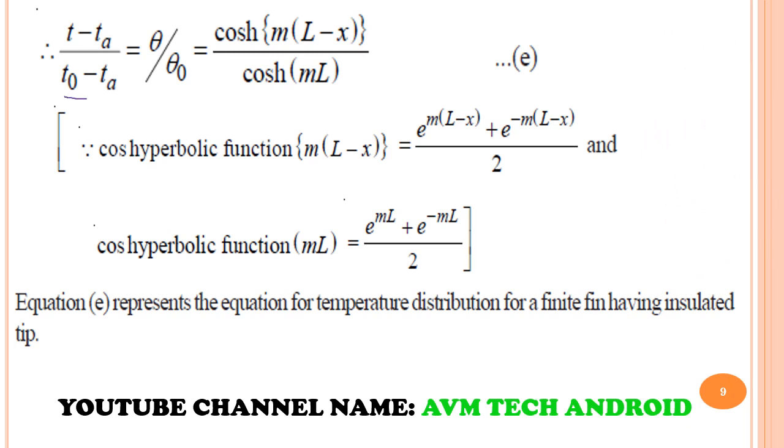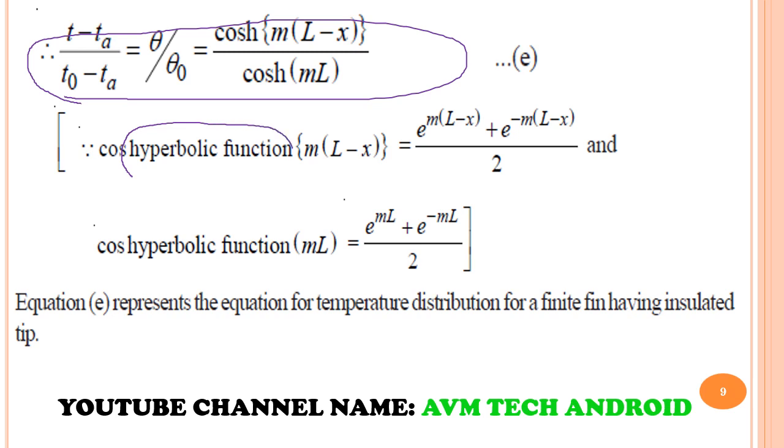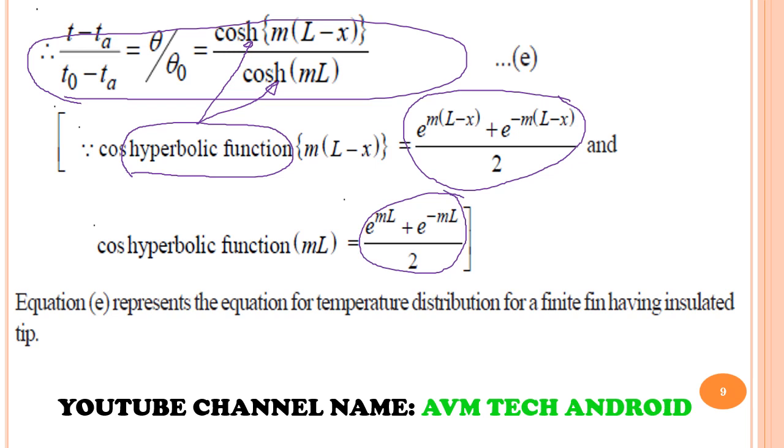So now it is clear, this equation number E: T minus TA divided by T0 minus TA equals cos hyperbolic m into L minus x divided by cos hyperbolic ml. Now this h is a hyperbolic function, either this or it is this, and its full expansion is shown here for both the cases. So this represents the equation for temperature distribution for a fin which is of finite length and having an insulated tip.